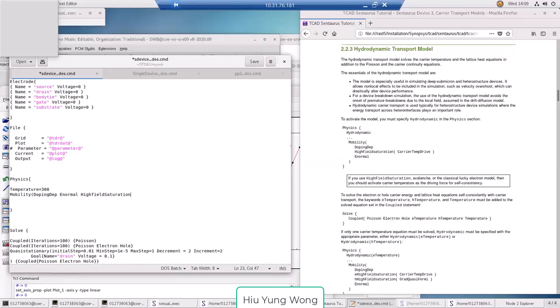In the silicon, when your electron becomes faster, it has higher energy, then it has more chance to lose energy through something called optical photon scattering. It's a quantum mechanical thing. When you have low energy, you don't lose energy that way. When you get enough energy, then you lose it faster. So the velocity will saturate.